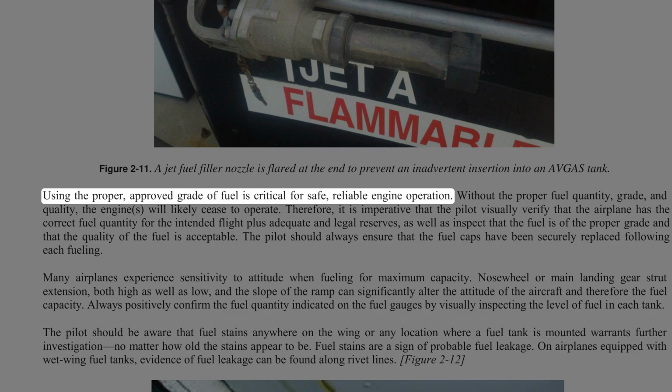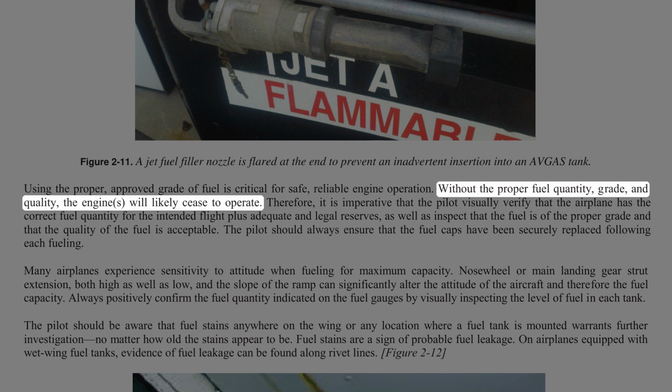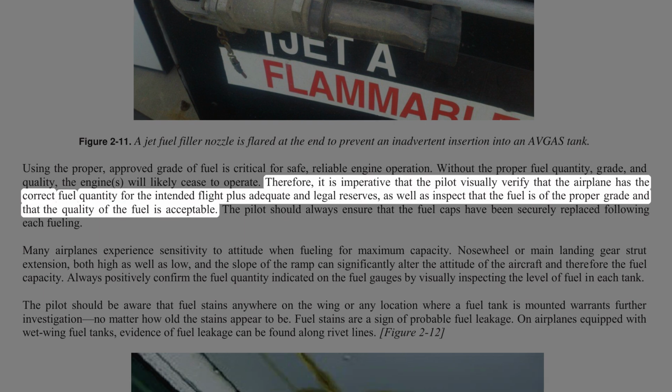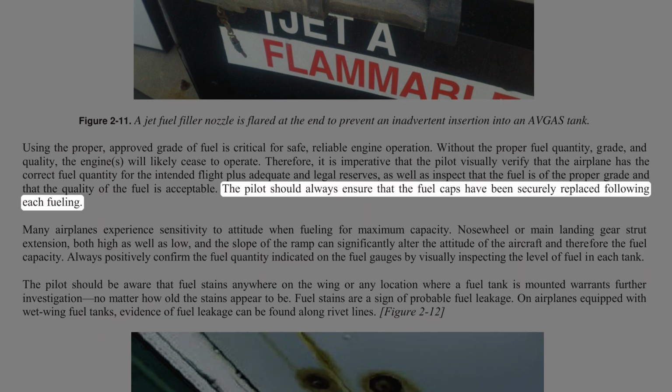Using the proper, approved grade of fuel is critical for safe, reliable engine operation. Without the proper fuel quantity, grade, and quality, the engines will likely cease to operate. Therefore, it is imperative that the pilot visually verify that the airplane has the correct fuel quantity for the intended flight plus adequate and legal reserves, as well as inspect that the fuel is of the proper grade and that the quality of the fuel is acceptable. The pilot should always ensure that the fuel caps have been securely replaced following each fueling.